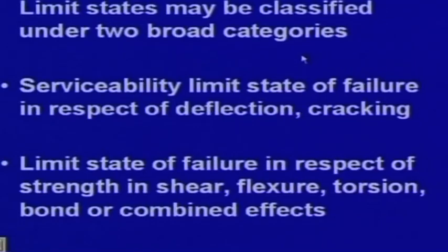One is the serviceability limit state, of failure in respect of deflection and cracking. The other is the limit state of failure in respect of strength in shear, flexure, torsion, bond or combined effects; axial will also come when we talk about columns.